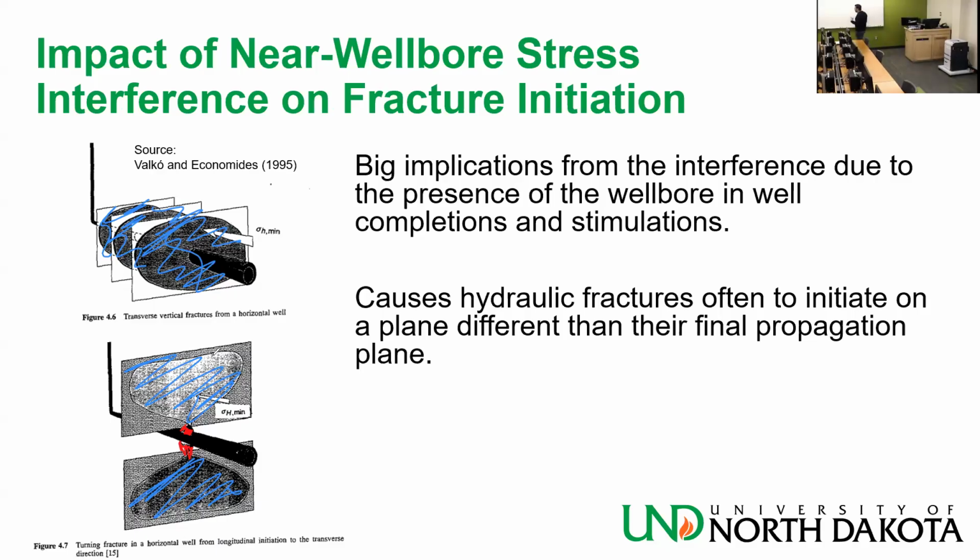And the obstacle to the flow is sometimes created naturally. You want it to be created when the fractures have grown sufficiently. You don't want it to be created as soon as you start pumping early on. And this twisting can be the cause of early screen out.